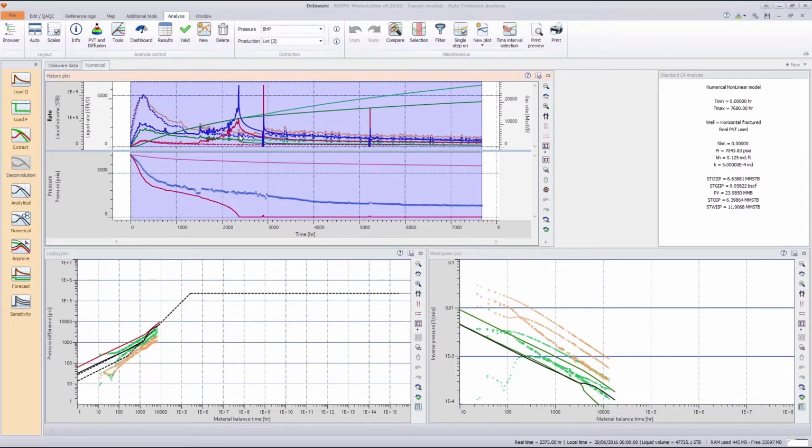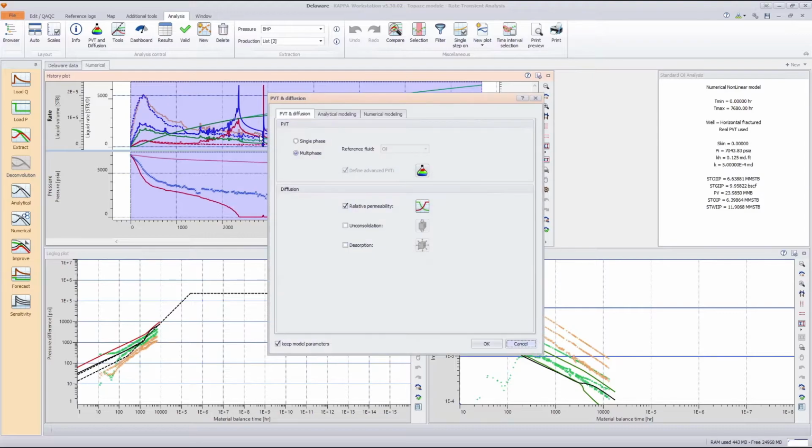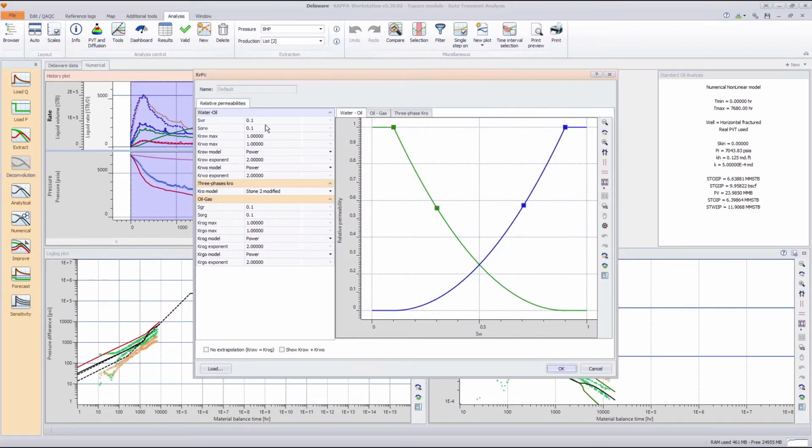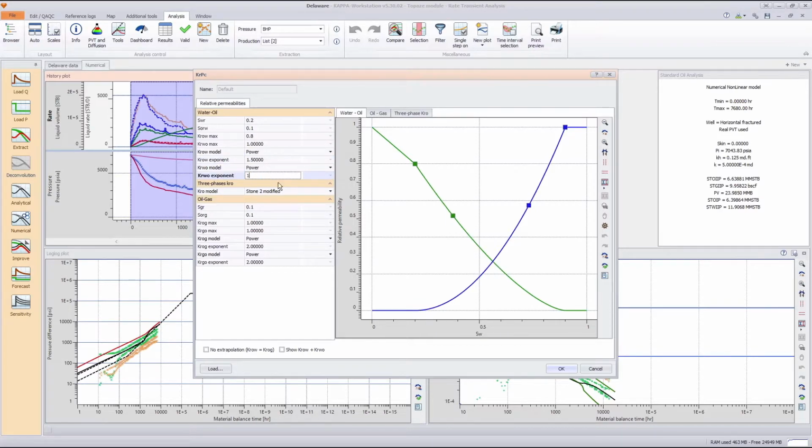And for the water and late time behavior of the model, we can use the relative permeability curves as matching parameters as well. Of course they are highly uncertain in unconventional reservoirs. So changing the exponents, the parameters, and the endpoints of the relative permeability curves becomes a matching parameter in this case. Here I can use some parameters that I've already gotten for this example. Just need to be careful. You see we get more streamlined flow, we lose less in the presence of multi-phase. So I type some parameters, 0.25, and the power changed to 1. So for oil and gas it's purely linear. And click OK.